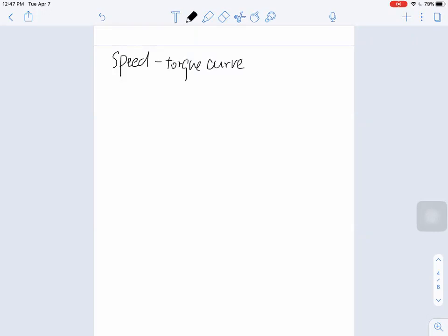Usually if you want to buy a DC motor, you are able to find the speed torque curve on the data sheet that the website will probably give you. And here, when we look at the speed torque curve, we want to look at what this curve looks like under a steady state when current is constant.